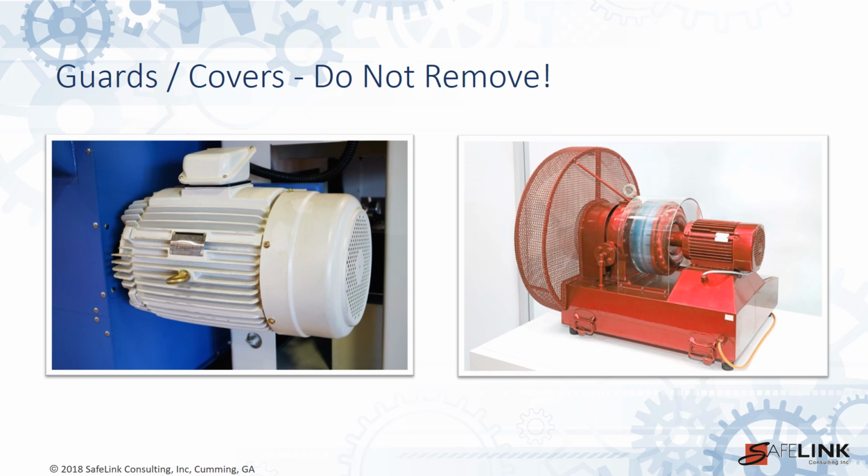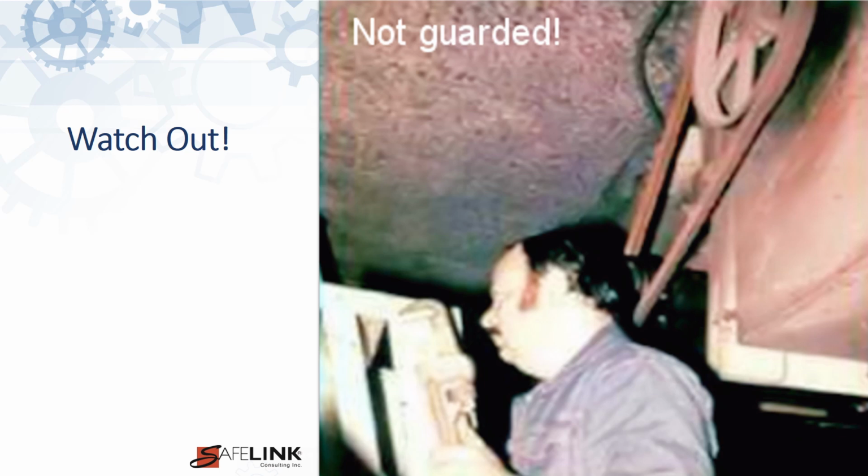Contact with unguarded machinery can result in amputation or even death. It is important to perform inspections of equipment prior to each use and implement a preventive maintenance program for equipment. Check for equipment defects and check all guards before each use to assure they are providing the appropriate protection. Never remove or bypass a guard. The belt behind this man's head must be guarded to prevent contact. Look at how close this man's head is to the belt should it begin running. It wouldn't be a pretty sight.